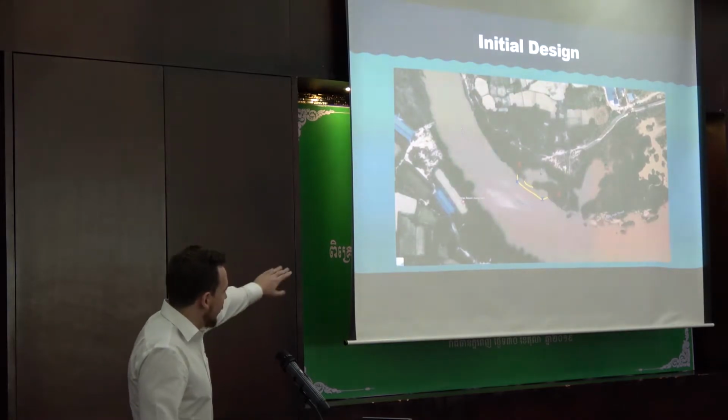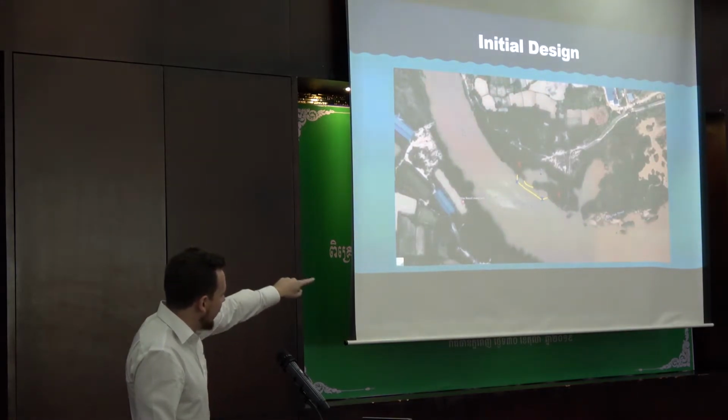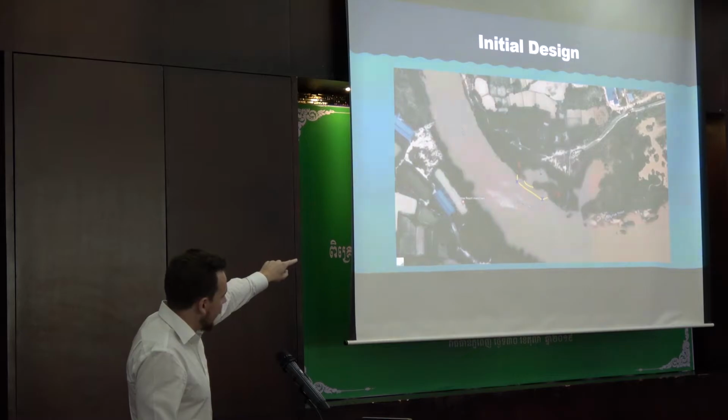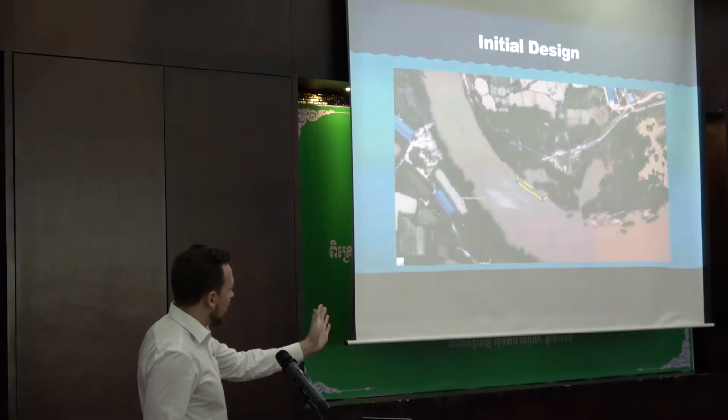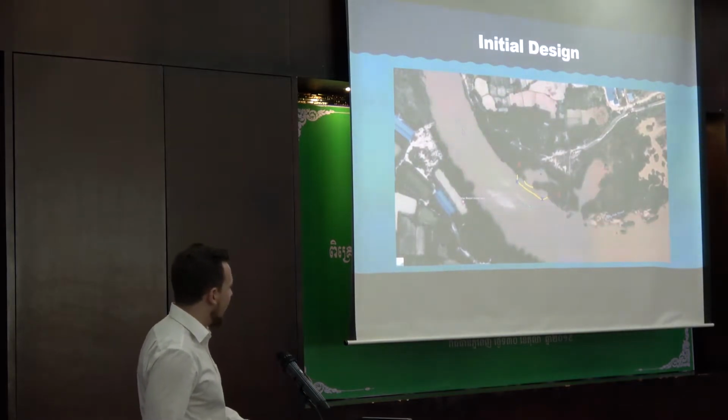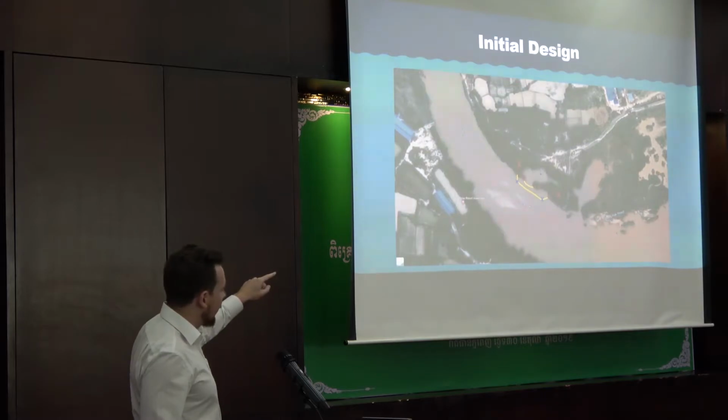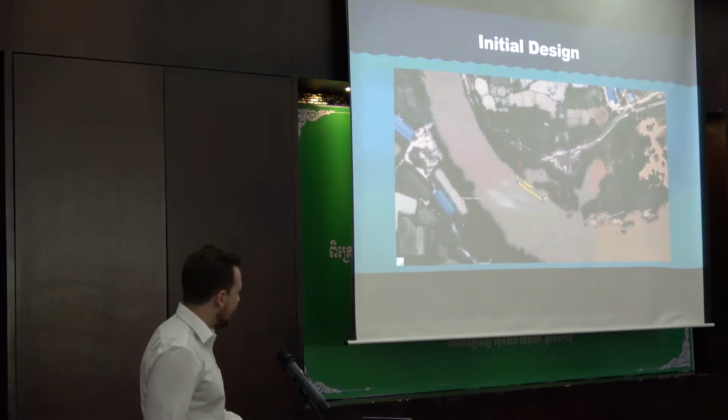We've got the preliminary curtain further out in the river. The idea was we were going to anchor it in place using river anchors to make sure that the strength of the current didn't push the curtain in towards the lagoon. And we had the curtain across the inlet to the lagoon anchored with land anchor points.